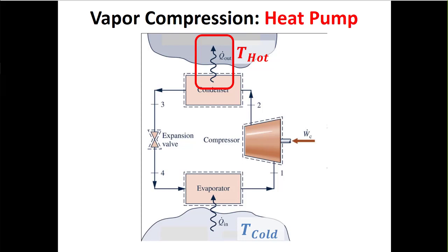But because we got extreme winters and extreme summers here in the Northeast, typically you have two different devices: an air conditioner and maybe a natural gas furnace, right? But the difference between the heat pump and the refrigerator is the energy benefit, right? So it's going to be the numerator in our coefficient of performance, right? So here we're going to have Q dot out, or Q dot in the condenser, or Q dot hot, divided by net power. But the analysis is exactly the same, right?